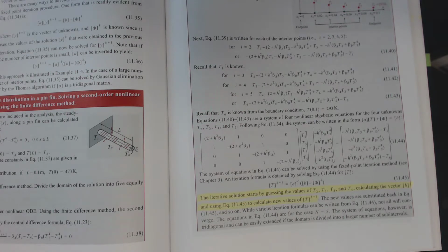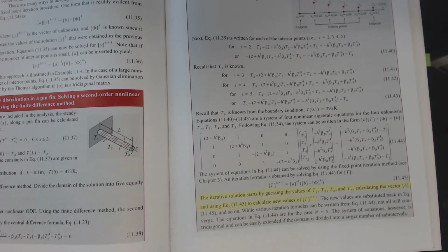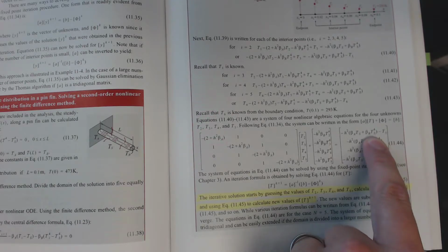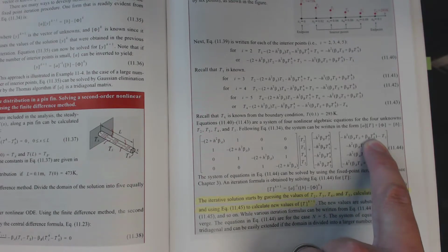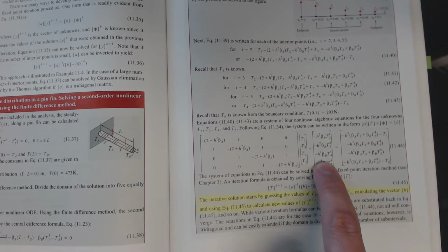So you can't use Gauss-Jordan directly. You can't use any of the linear inversion and multiply methods because it's a nonlinear equation. The temperature to the fourth, so T2 to the fourth, T3 to the fourth, T4 to the fourth, etc., takes that luxury away from us. Surface temperature to the fourth, fine. It's constant. That's not an actual variable. It's known. These are the nonlinear coefficients making life more challenging.